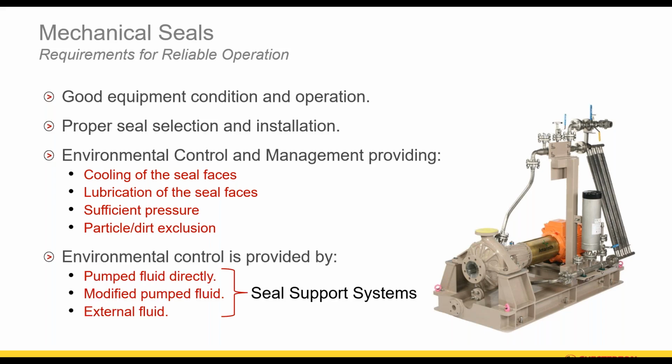And then realize the environmental control can be provided from several different sources. We may use the pumped fluid directly. We may modify that pumped fluid, or we may use an external fluid. And again, this is what's known as the seal support system.